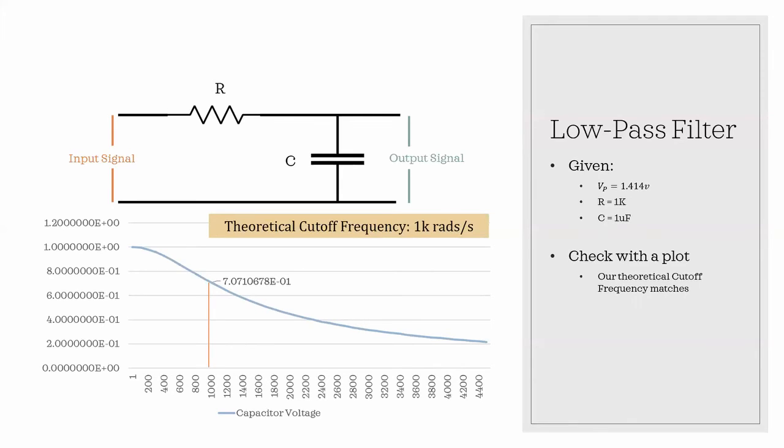And this circuit input was designed specifically so that we could see that it is 0.707, because if you take 1.414 volts in alternating current, the RMS voltage just is 1, because remember, it's the peak voltage over the square root of 2, so 1.414 over root 2 is 1. And then, now that we have our input, we get our half power frequency, once again, a factor of root 2, 0.707. Nice.